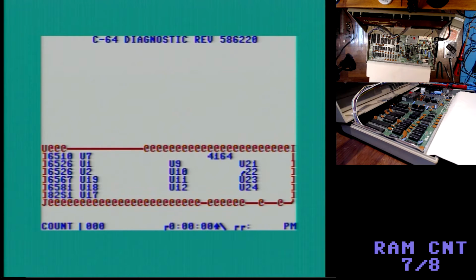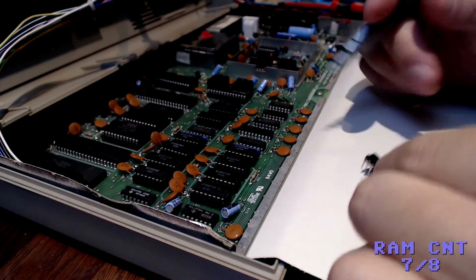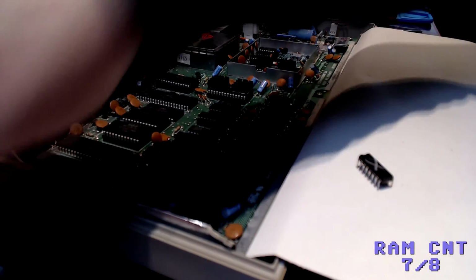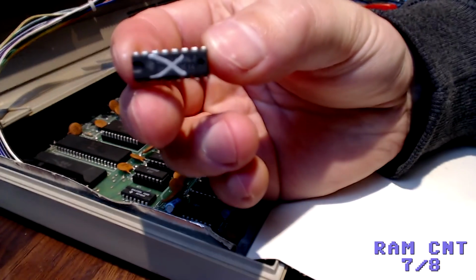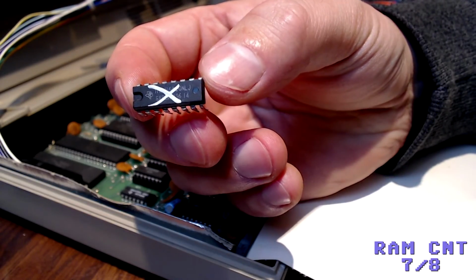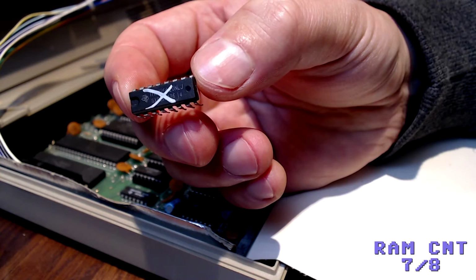I was expecting at least one of the RAM chips to be defective as well as the flip-flop over here, so I guess that is what I expected. It's just funny that it's the last RAM chip we test. Definitely bad, and we'll give it a big X. Big fat X. I think I'm gonna do like Adrian's Digital Basement and make a dead parts bin where I'll put this and future bad chips.